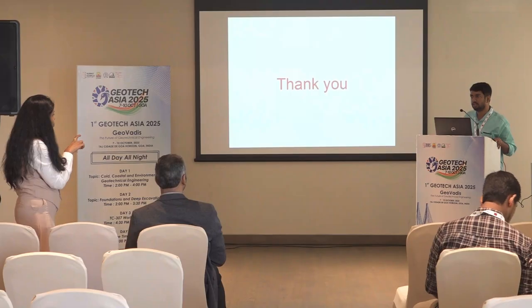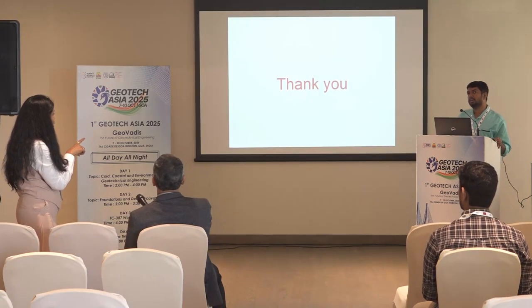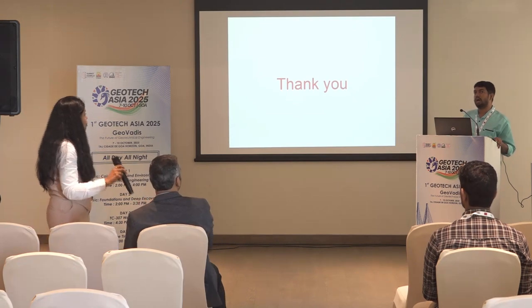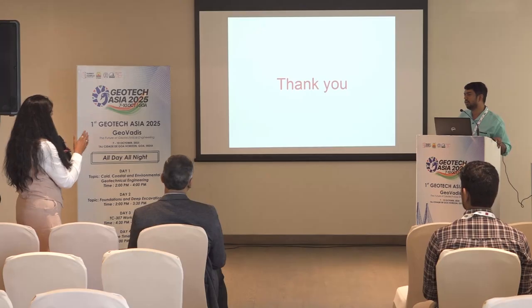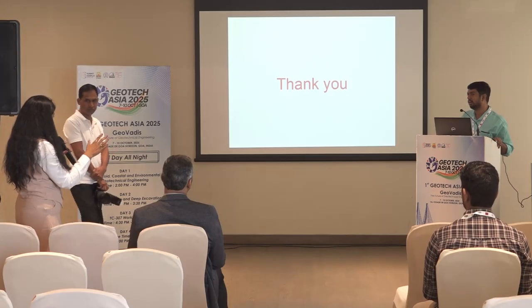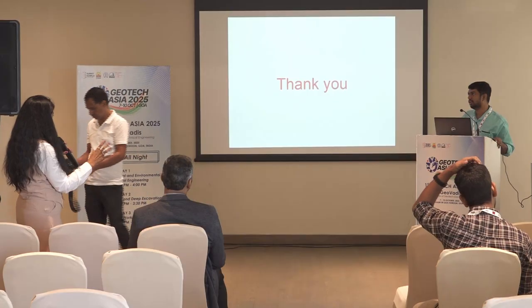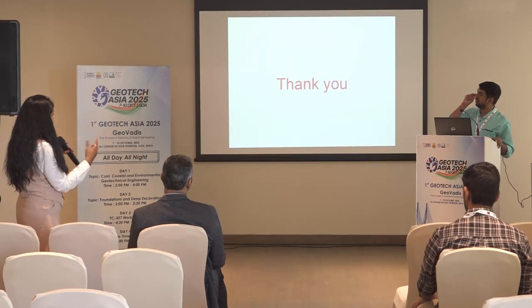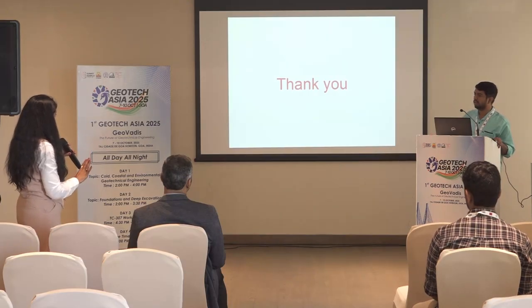Instead of a socket of 1.2 meter, oh, there was a socket of 1.2 meter for the piling that you have shown there. But I am a little bit surprised that you're telling there was soft soil, and the adjacent bore log was having some weathered rock, right? And because of that, all these axial forces have increased on the pile. Because the pile load is 97, it's a huge amount. And the depth is huge, like 22 meter. Yes, 22. And then you have a socket properly.